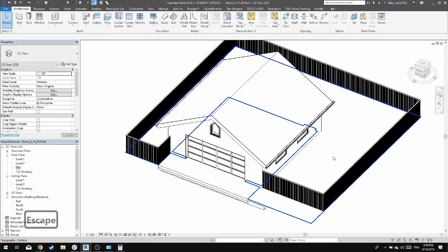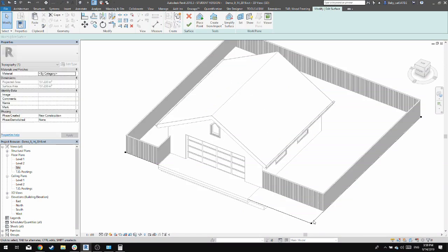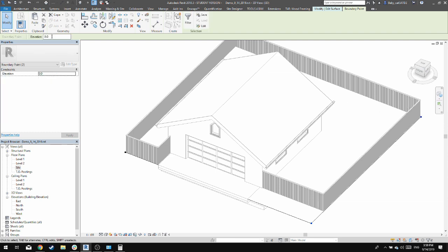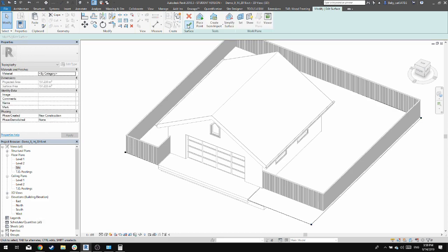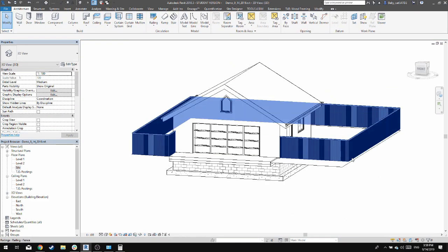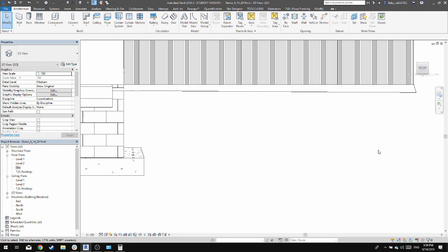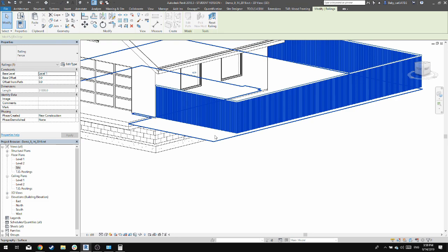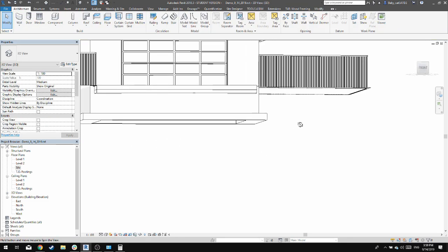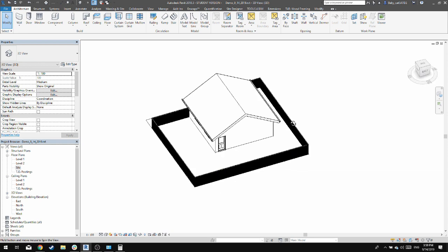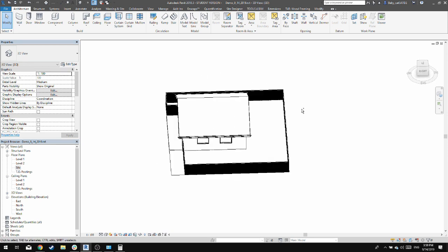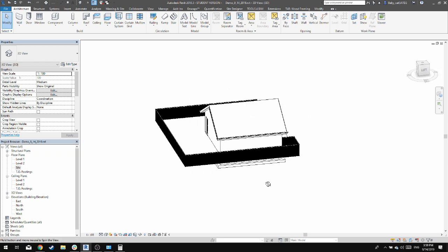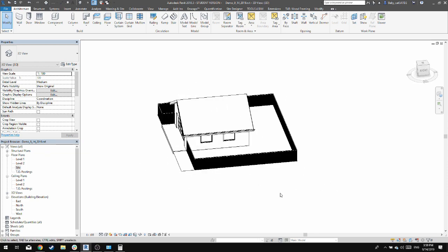And if the site wasn't flat, so if I go into here quickly, edit surface, and change the height of these two points, so let's say negative 100, that goes down 10 centimeters, you'll notice that the fence does not stay on the topo surface. What you can do is select your fence, pick new host, and select the topo surface, and it'll stick itself onto the surface, and it'll be nice and pretty. Then we can press Control S again to save, because we did something cool. And I think this is probably a pretty good place to leave it for this week.